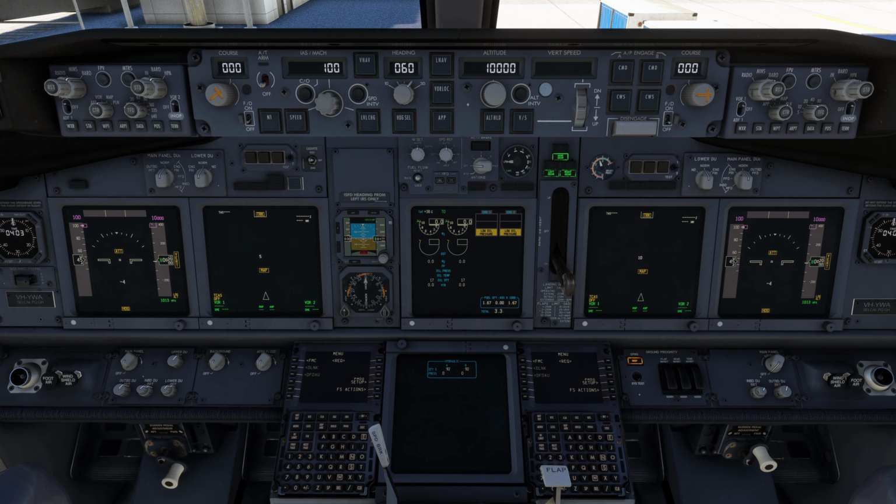Both overheat protections monitor different parts of the air system, so you could have both systems fail. The trim air also gives false warnings, and in the real plane, Boeing even put out an FCOM bulletin titled Nuisance Zone Temp Light Illuminations. So let's break down ways we can avoid all this step by step.